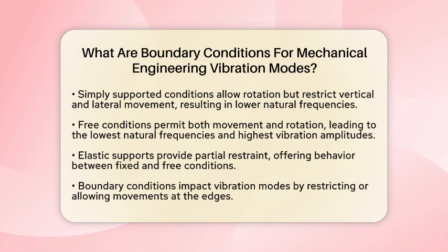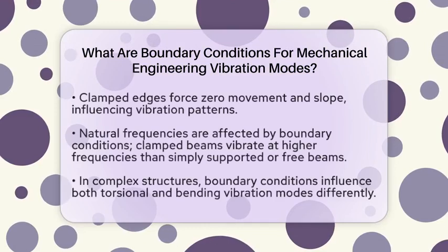Now, how do these boundary conditions impact vibration modes? They affect the mode shapes by either restricting or allowing certain movements at the boundaries. For instance, a clamped edge forces zero movement and zero slope, shaping the vibration pattern accordingly.